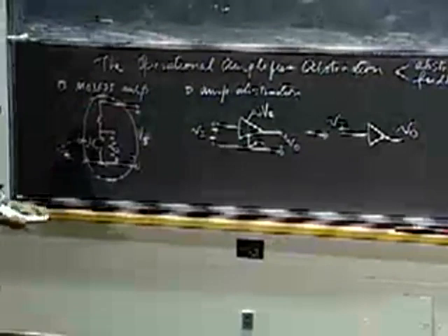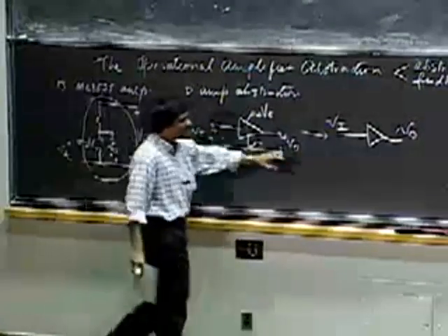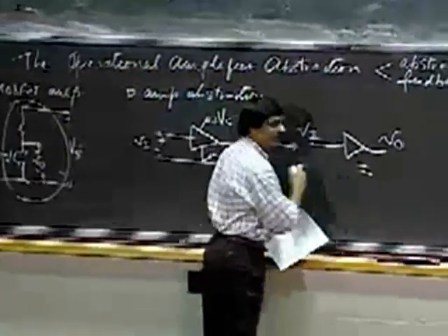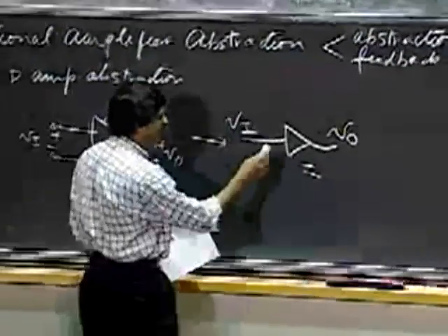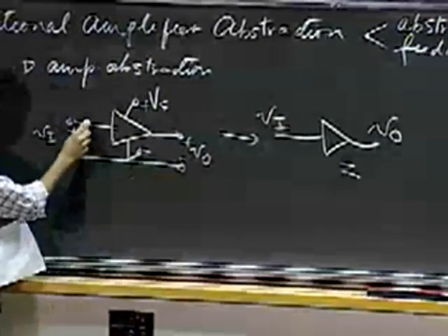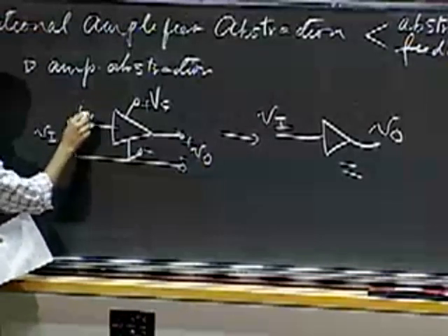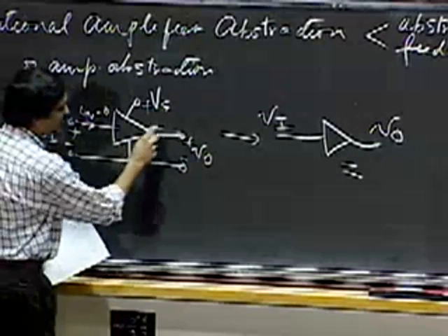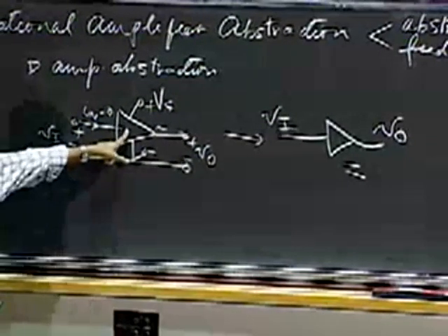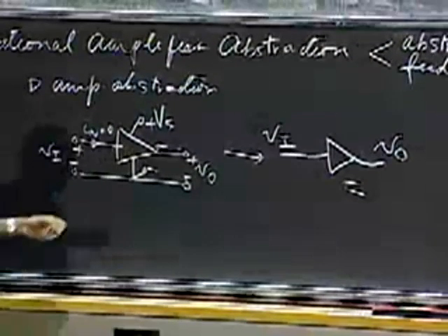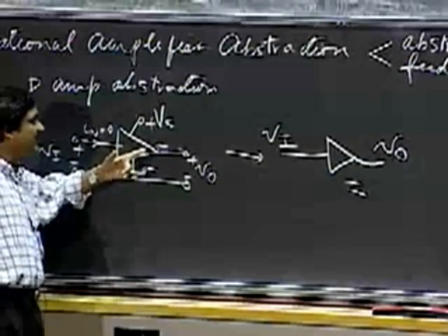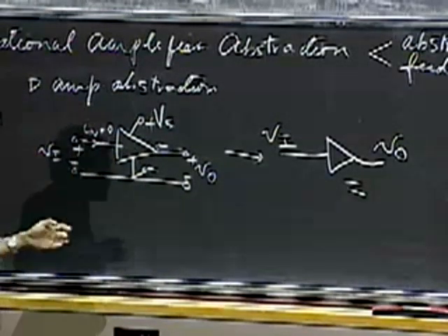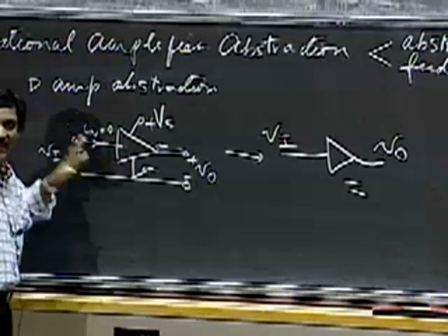So what we can do is, provided we know, we can abstract out the relevant properties of this block and expose them outside. And the relevant properties might well be that, let's say here, I in is always 0, right? I can also express to you the gain of this amplifier. I may also be able to tell you a Thevenin equivalent for the output. Okay, so there are some properties that I can give you that will let you use this building block abstractly.